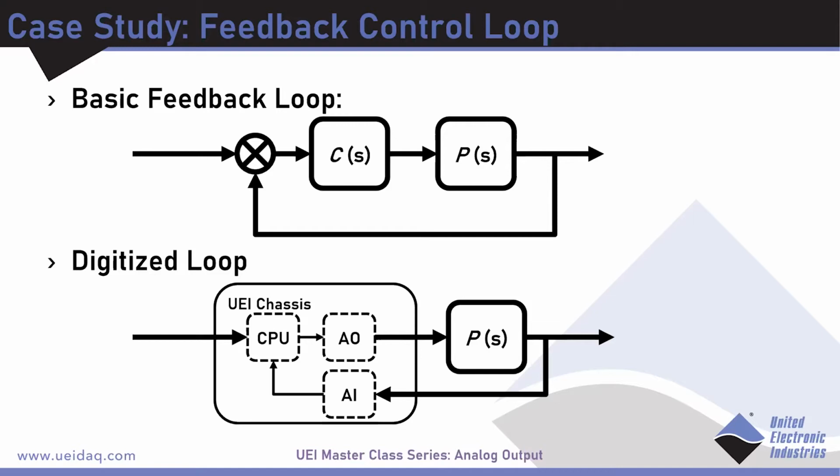And of course, this comes with a couple of other advantages as well. Normal feedback loops might take the form of a built PCB, right? You've got resistors and capacitors, and that builds up your feedback loop. However, adjusting the parameters of your loop might mean something as easy as tuning a potentiometer while it's on your desk, but that could potentially get more difficult if that device, for example, is out in the field with a customer, right? Do you figure out how to get that device back? Do you tune the potentiometer to be something else? Digitizing this process makes our lives much easier in a lot of different ways.